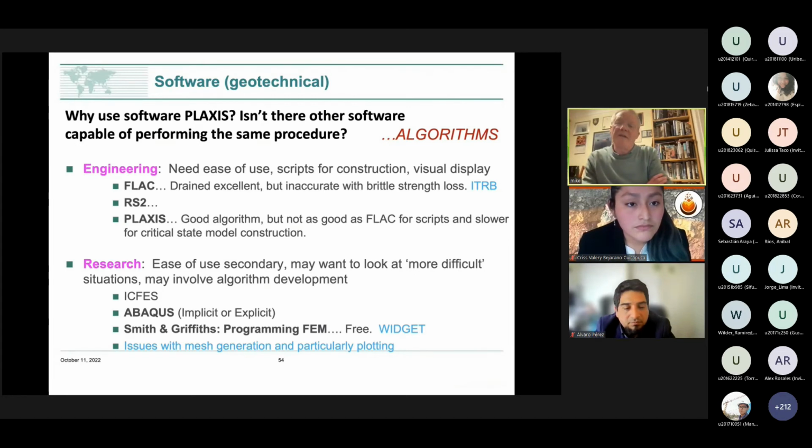Well, there is not one mathematical procedure for doing that. There's a range of procedures we use within the finite element method: viscoplasticity, tangent stiffness, and a few more. And some of those procedures are easier to code. Some of them have better accuracy. Some of them are more stable. So the various software houses have gone down different avenues for which algorithm they use to solve the equations.